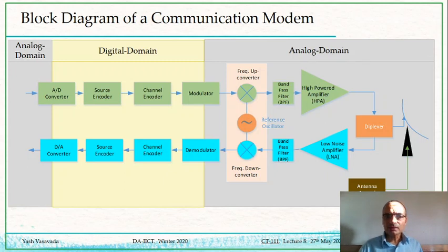complete the earlier discussion or earlier model that we had, in which we took a binary phase shift keying signal, which was one dimensional, and we made it two dimensional by introducing a quadrature component, and we called it S_I and S_Q.